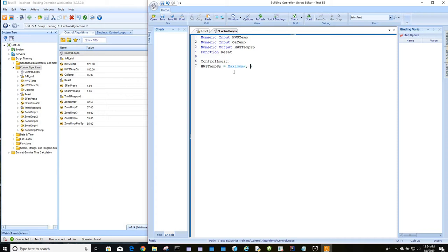take the largest of these two, in order to make sure that our output value never goes below 120. And then we'll take the smallest of the two to make sure that if our output ever goes above 180, we take the smallest of this, so we would take 180 at that. In that instance, if our output turns out to send a set point of 200 degrees, well, we don't want that, so we'll take the minimum of the two. We'll take 180,